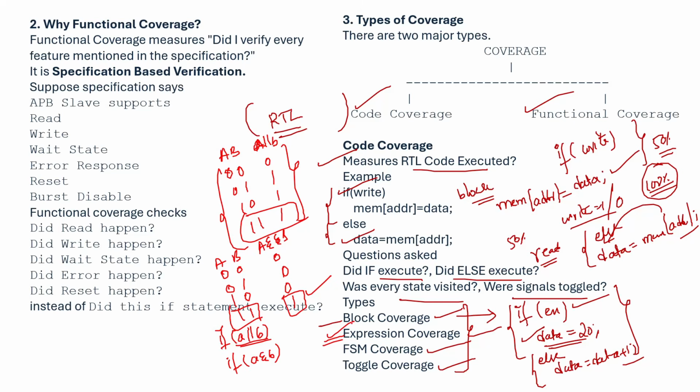That will tell you the expression coverage. And then FSM coverage, that means finite state machine. This finite state machine, you know, right? Some conditions are called in your state machine, S1 is a state in pattern detection, you know. S10, S101 and S1010. These are the states, and I am taking an enum of S1, S10, S101, S1010, and then some idle state you are taking.